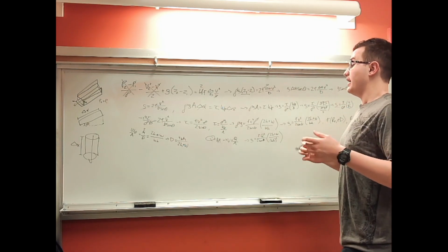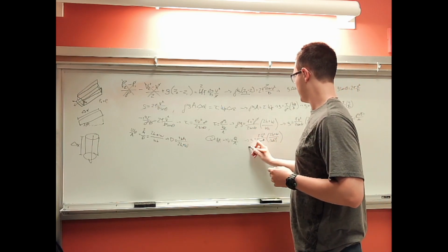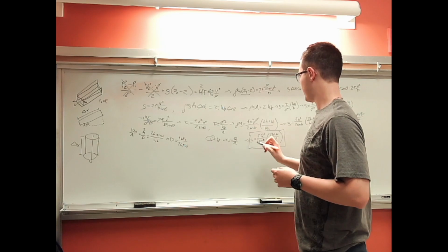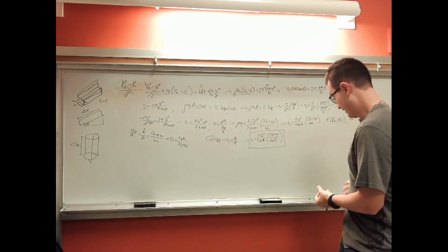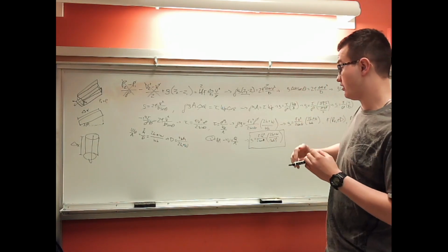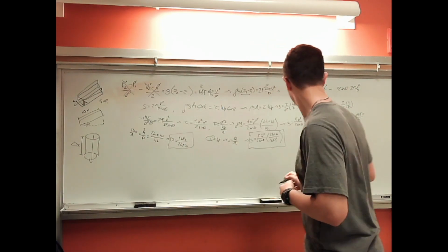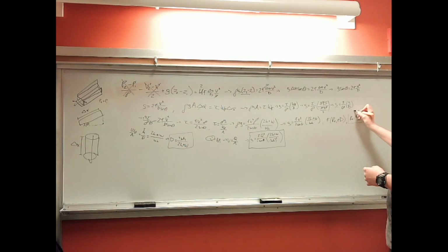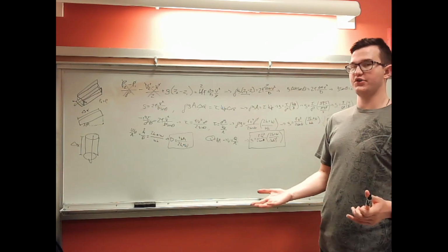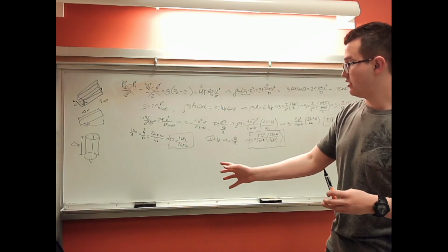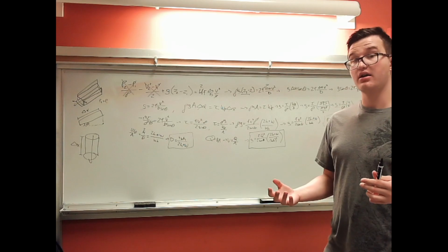So now we have this gravitational constant, which contains height in it, so we can use that in our code. We have a diameter equation, which also has height in it, and we have a Reynolds number that can be used to find the Fanning friction factor here in the Churchill equation. So with all of that done, we're going to move over to the coding now.